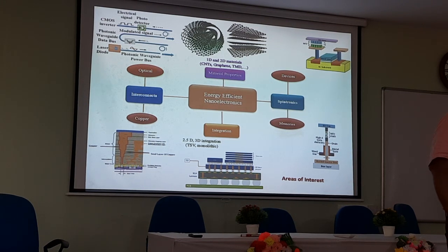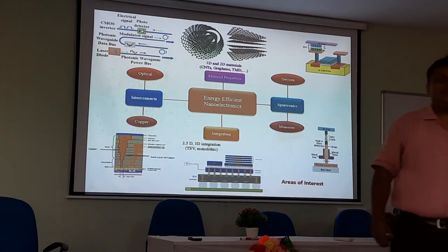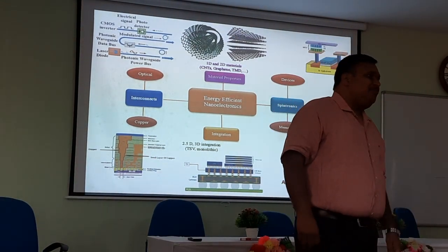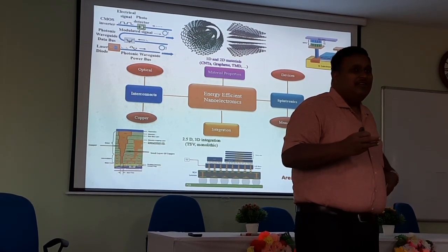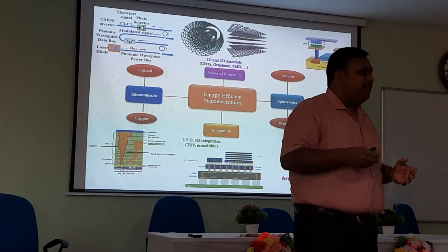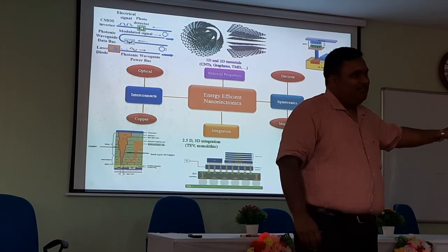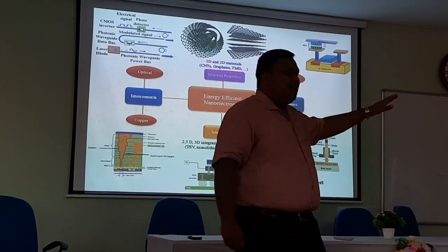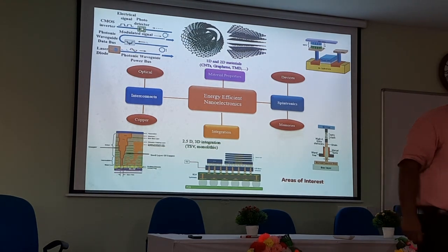Now, what important thing are you seeing here in comparison to DRAM? What I am trying to convince you of is that we often switch from SRAM to DRAM for size, density. Otherwise, DRAM is worse as far as speed is concerned. It can never match SRAM. When it comes to the core of a CPU, you will always go with SRAM.